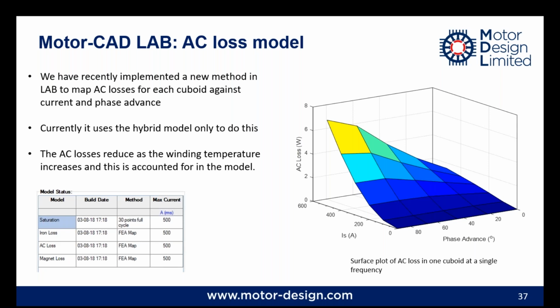We also scale it with frequency, and this goes back to our scaling discussion before, where we had one section where it's resistance limited and then inductance limited, and we can affect the scaling depending on what level the eddy currents are at.